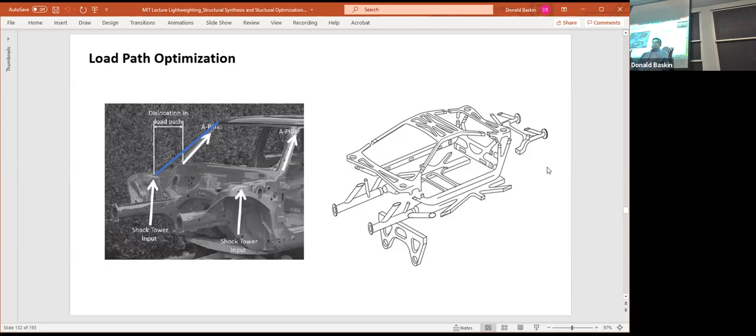When you have a car and you have springs that are pushing down on the wheels and the suspension, the main forces that go into the chassis go through those springs. There's also a damper in there too, so you don't get a resonant frequency on the freeway. Those forces feed into the body structure, these things we talked about before called the shock towers, right? So you can kind of imagine the main forces are coming up through these shock towers.